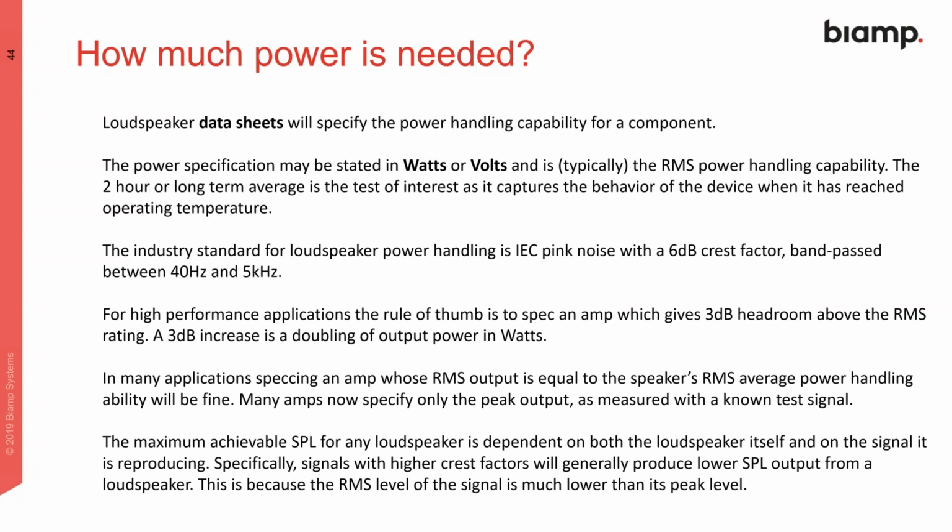And they back it down, and when they get one that doesn't fail, then they say, okay, now we're in the ballpark, and that becomes the power handling for that speaker. So it's got pink noise with a 6 dB crest factor.